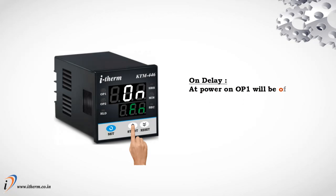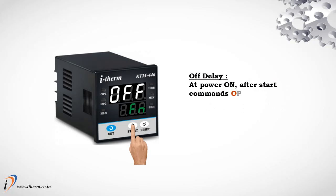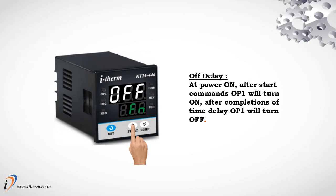On delay. At power on, output 1 will be off. After the start command and completion of the time delay, output 1 will turn on. Off delay. At power on, after the start command, output 1 will turn on. After completion of the time delay, output 1 will turn off.